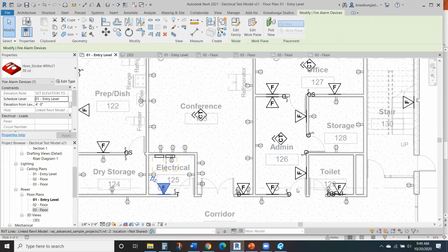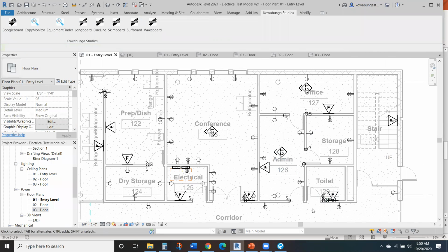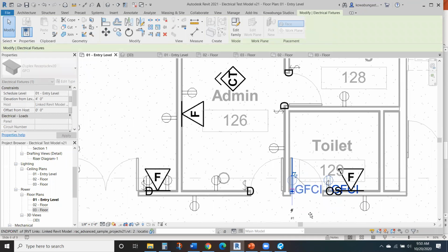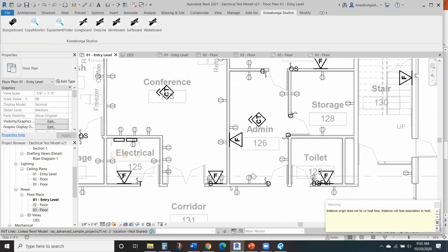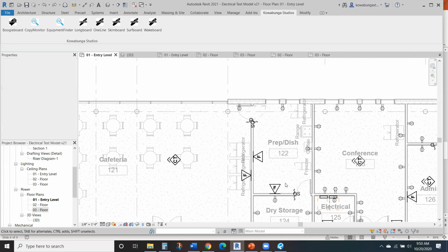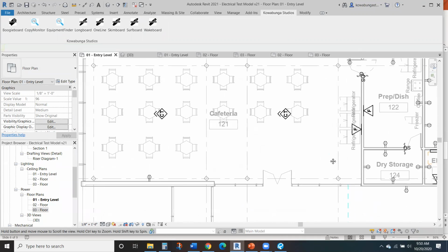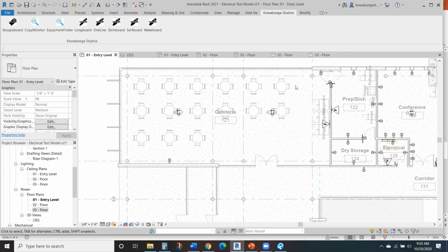and in some of these, you might have to, worst case, delete, right? This is worst case. Or you pick new, say, hey, we really want it here. Boom, boom. Layout done, right? You're checking through everything and seeing what you're doing. So there's your GFCI, right? That was right next to the door with your occupancy sensor switch. Again, I'm showing everything here in this view. So again, delete, we're good, right? We're here, we're moving. Nothing on a curtain wall. See, this is all curtain wall. So we're good.